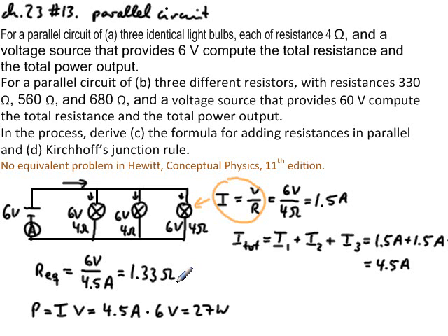So we have 4 ohms, and we add 4 ohms and another 4 ohms, and the total resistance is supposed to decrease below 4 ohms, of course. Apparently it is 1.33 right now. Overall resistance is lowered with each added path between any 2 points of the circuit. This means the overall resistance of the circuit is less than the resistance of any of the branches, and that's true.